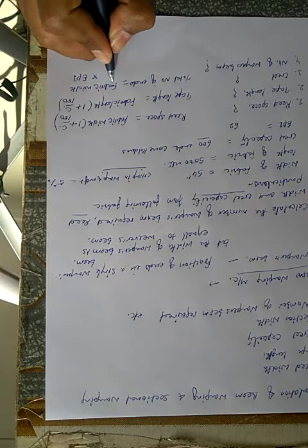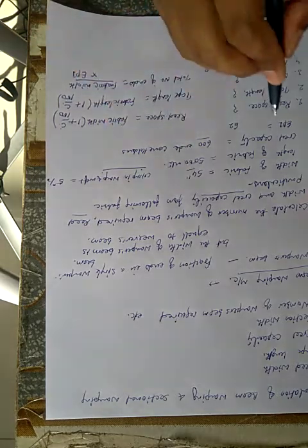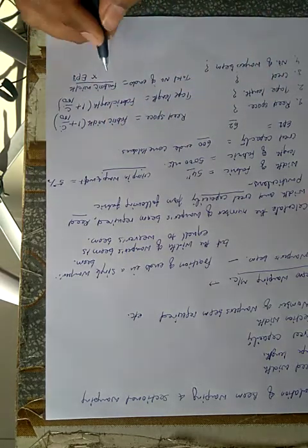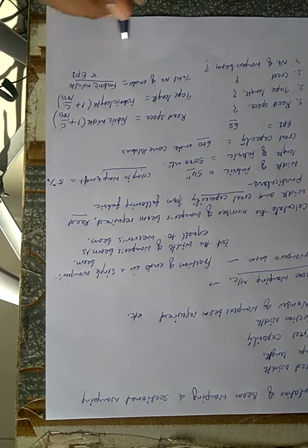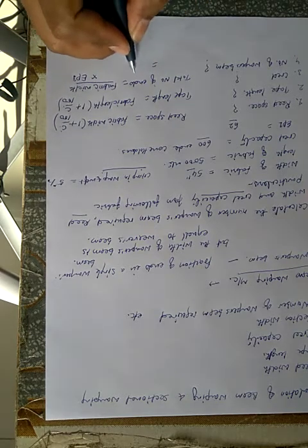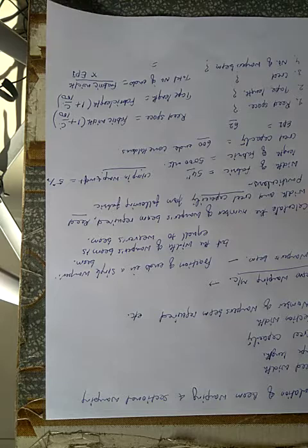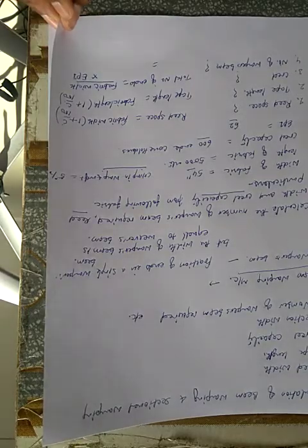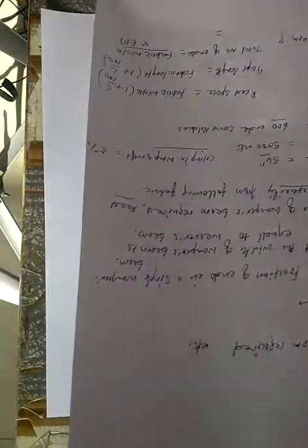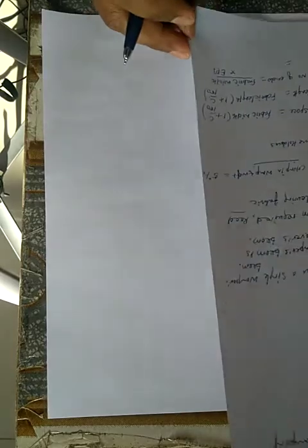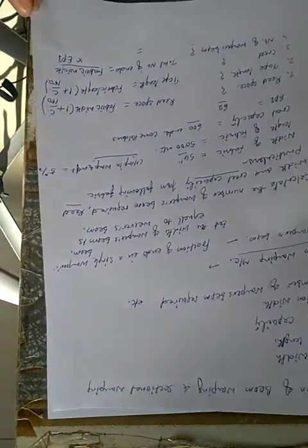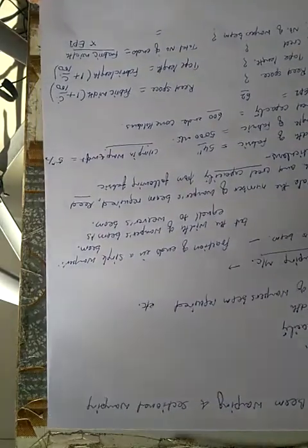Here we have fabric width in inches and we have EPI. When we multiply fabric width with EPI, it will give the total number of ends. Then we will calculate creel required and then number of warpers beam.